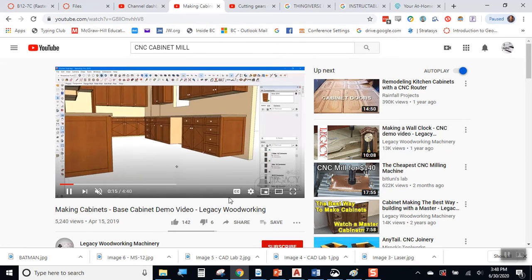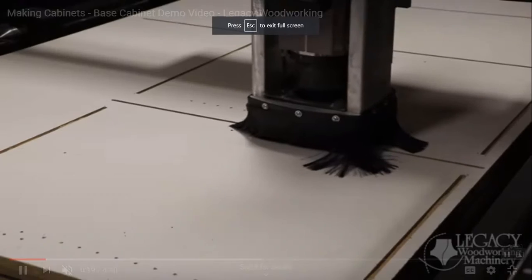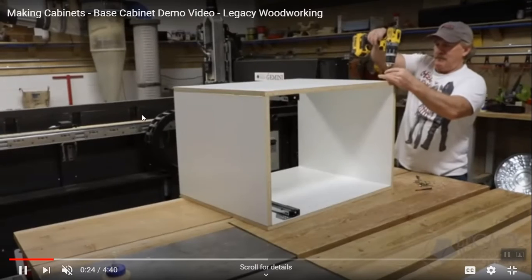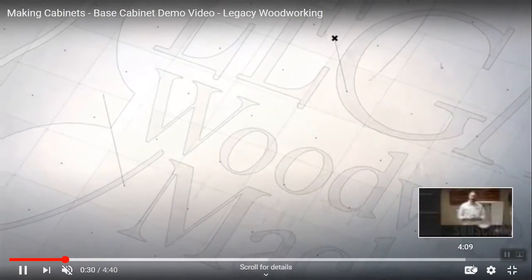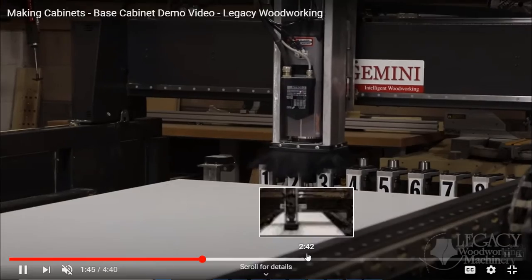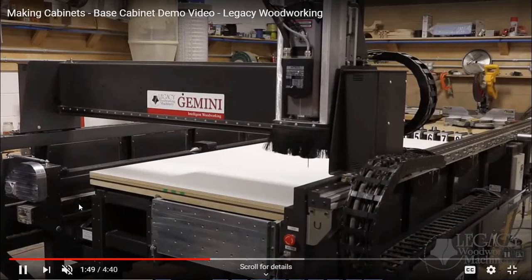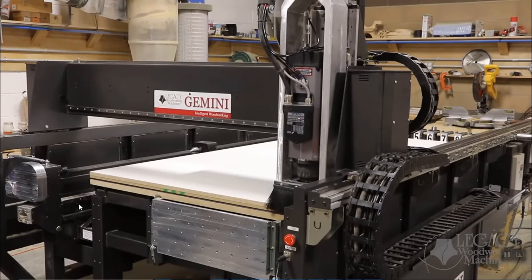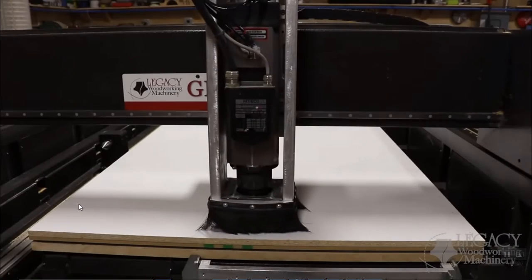Working with cabinetry, there are CNC tools that do cutting. This is a CNC Panel Router, and the panel router cuts the different parts of the cabinet so that you don't have to cut the stuff on a table saw, which is pretty cool. So that panel router goes over to the gantry, it picks up the correct cutter, correct size it needs, and it plunges into the material, and then it drives itself in the XY axis, and it'll do cutting.